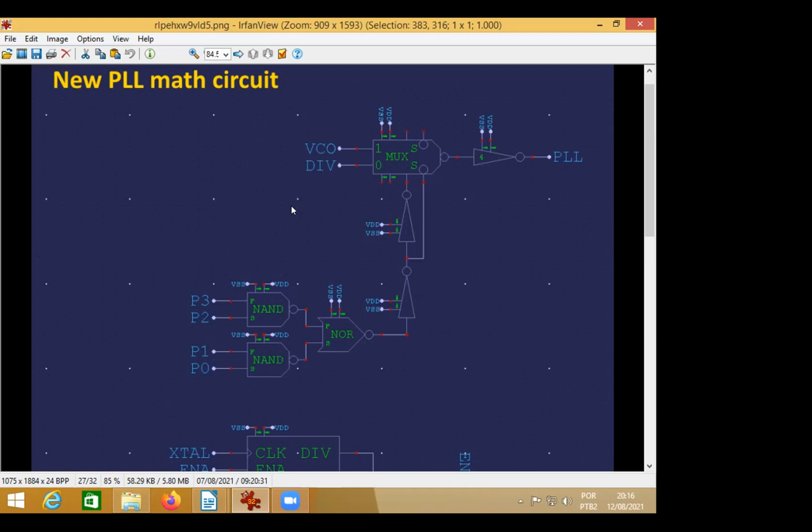When you inject one higher bit of the counter into the chain of ORs, the chain of ORs will act just like a shift register in my mind, or just part of a ring oscillator. Imagine you can put one into a branch of a ring oscillator and set all the outputs to 1 and inject the faster clock into the middle. While the ring oscillator is shifting out, if you don't cut the slowest one, it will keep shifting only the slowest frequency.